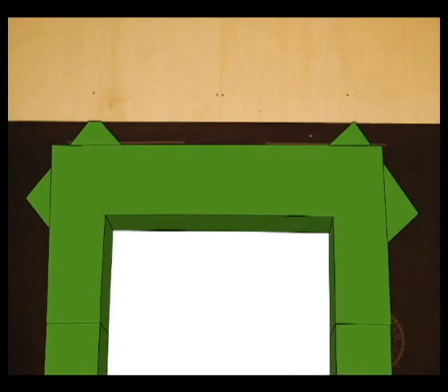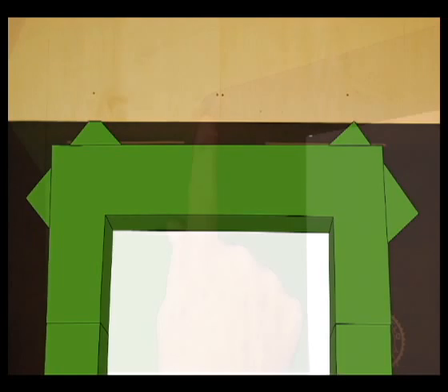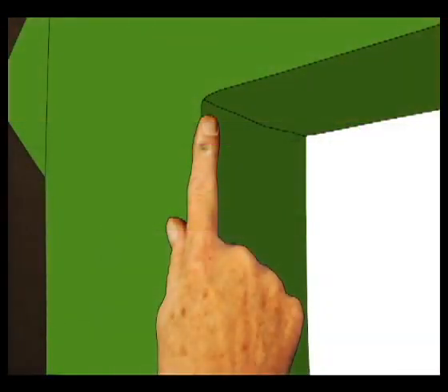Next, install the waterproofing material or flashing across the top of the window rough opening. Make sure to overlap the side waterproofing material or flashing shingle fashion. Make sure to cut and fold the top piece of waterproofing material or flashing to make a tight corner.